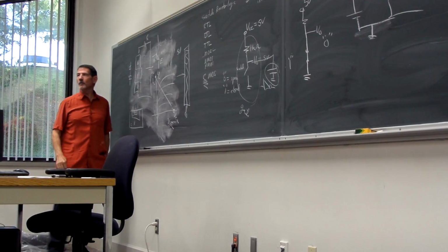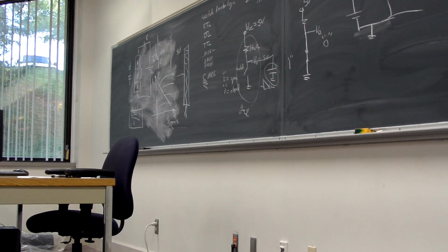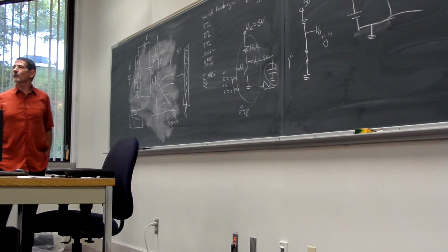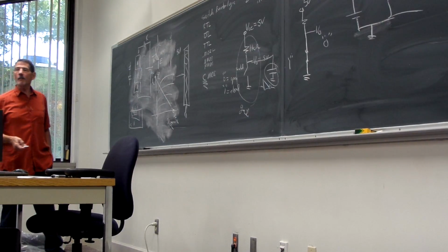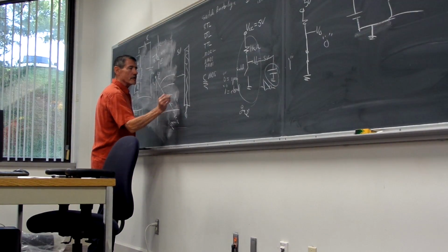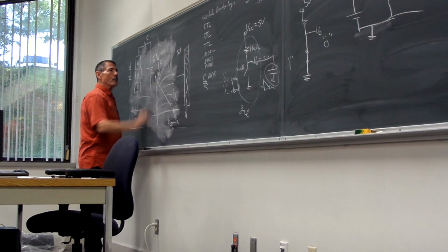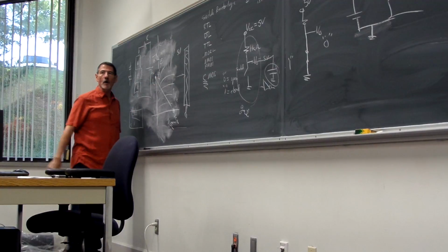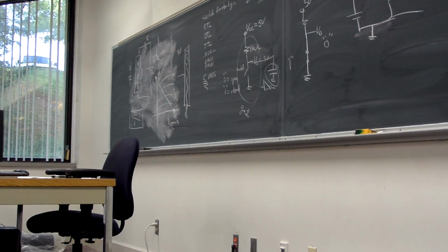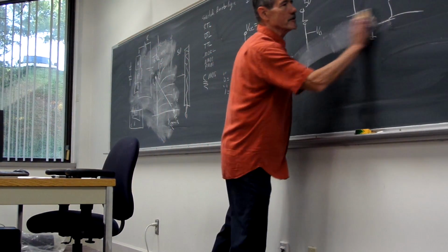You understand that that gives you a load line there, just like I drew a load line over there on our diode circuit. Right? And so where you operate on this load line depends upon how much current you're dumping in. If I dump in absolutely 0 base current, I'm operating here. If I drop in a whole bunch of base current, I'm operating over there. Everybody all right with that? Okay. So this is a BJT transistor. Now let me show you a MOS transistor.